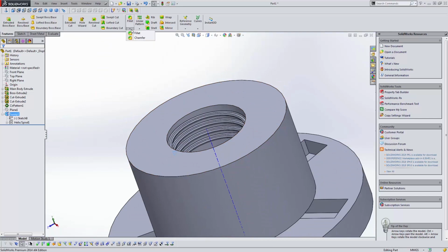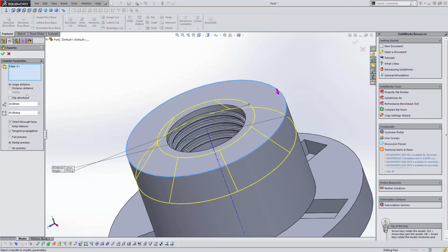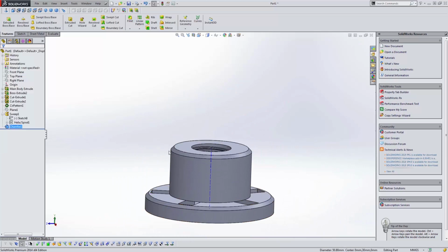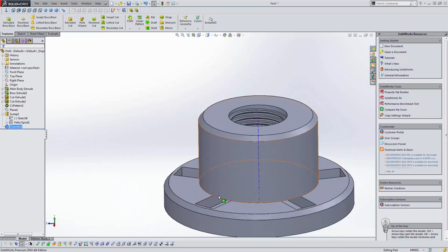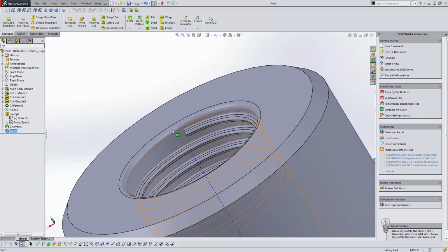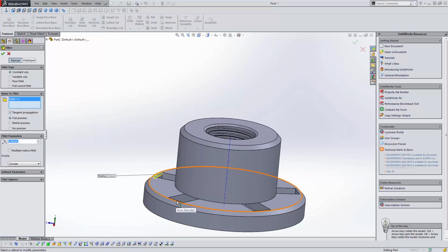For instance, some tools that are really interesting are the fillet, or chamfer. So chamfer is going to give you this. No, let me delete that face. So chamfer is going to give you this nice corner, squared corners, and you can get some cool results with that. The fillet, it doesn't like that. We have to put less of a radius in there. It gives you that nice rounded look. This is fun for 3D printing because a 3D printer can get some of these shapes really well.